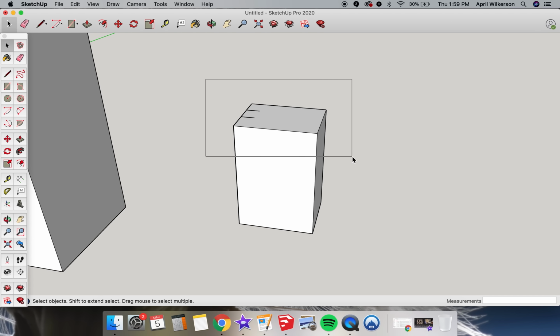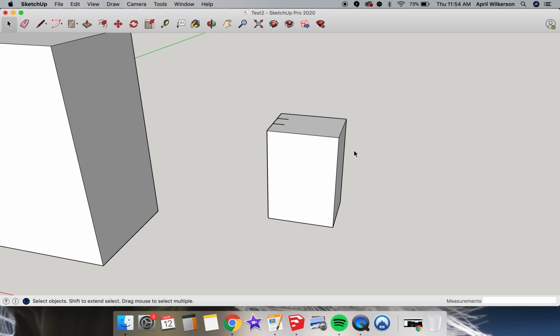Let me show you the circle tool, which of course is used to draw circles. It's this icon here, but the short key to use is V. So hit V to bring up the tool, then click once on any surface to start drawing. You can pull out, then click a second time to drop it. If you want an exact hole size, you can click once to start the tool, then type in the radius of the circle you want to end up with. Not the diameter, but the radius. So if you wanted an 8-inch hole, you would click once, type in 4 inches, and hit enter.